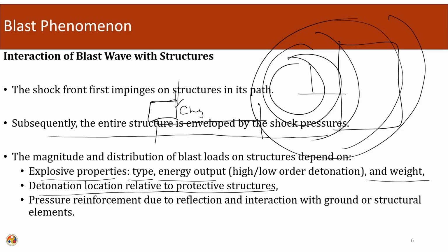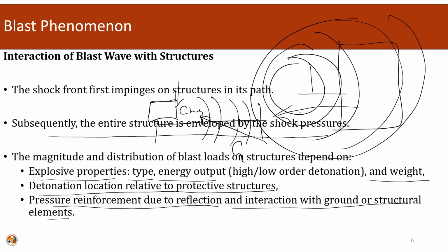After that there is an interaction between the blast wave and the structure. Due to this there will be a pressure reinforcement due to reflection and interaction with the ground or structural element. As this wave tries to reflect from the ground or from the structure, there will be an increase in the strength of the blast load.